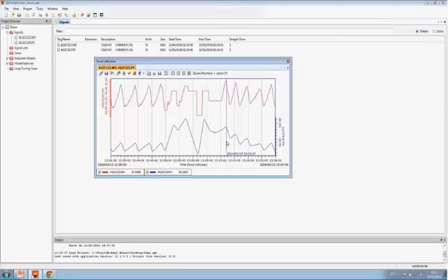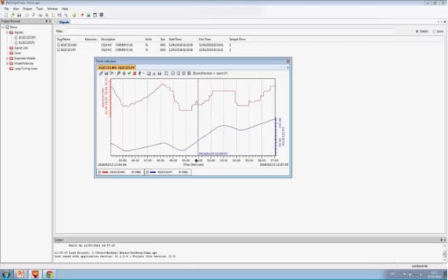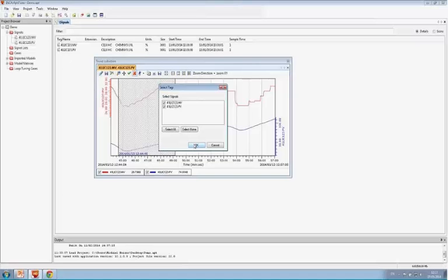Now, I recorded this data, and this data contains closed loop and open loop behavior. So to get my modeling correct, I need the open loop data only, and I'm going to select the open loop data by making the other data bad. I'll go to this point here, make this bad.